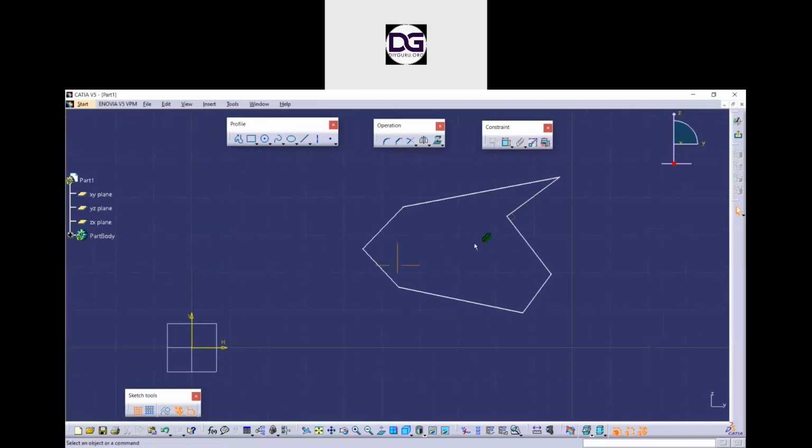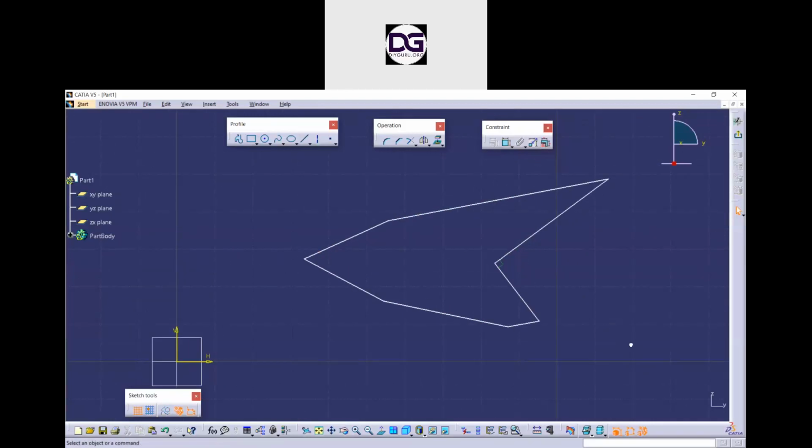To undo this I will just click on this paperclip option and delete this. So now these are not fixed together and I can change the single edges or points. So that's the fixed together option, fixed together constraint.